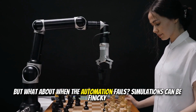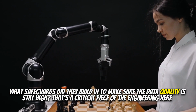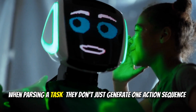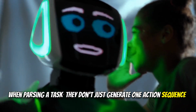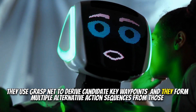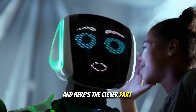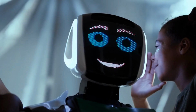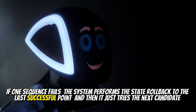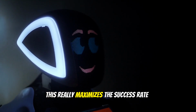But what about when the automation fails? Simulations can be finicky. What safeguards did they build in to make sure the data quality is still high? That's a critical piece of the engineering here. When parsing a task, they don't just generate one action sequence. They use GraspNet to derive candidate key waypoints, and they form multiple alternative action sequences from those. And here's the clever part: the robust retry mechanism. If one sequence fails, the system performs a state rollback to the last successful point, and then it just tries the next candidate sequence. This really maximizes the success rate.